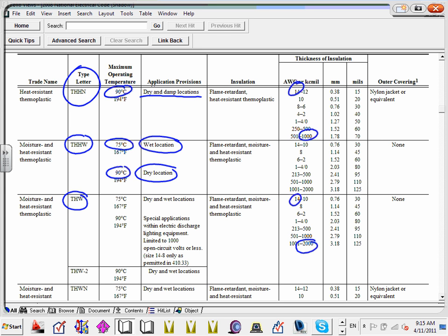A lot of contractors, guys, buy an insulation that says THHN/THW. So Spencer, they carry one type of conductor. You can use it inside, it will be rated for 90. If you're using it outside, it's the same conductor, because it's double rated. Use it inside or outside, no problem. Can I use a wet location cable in a dry location? Yes. So please, if you don't know these, guys, please highlight them.